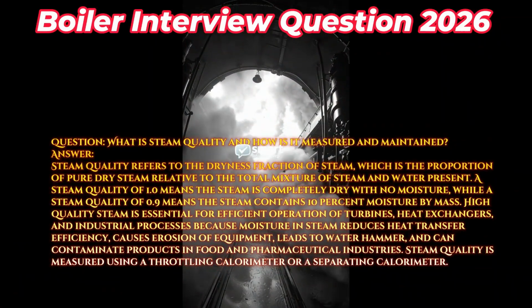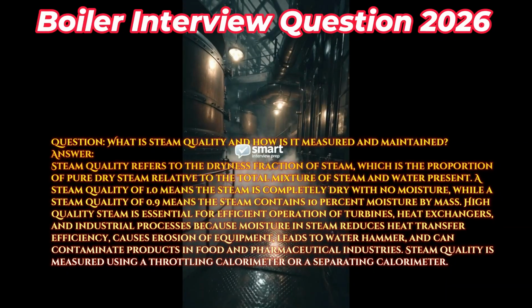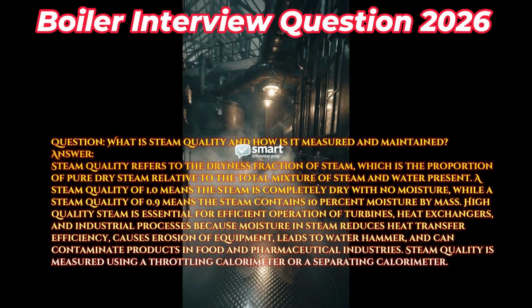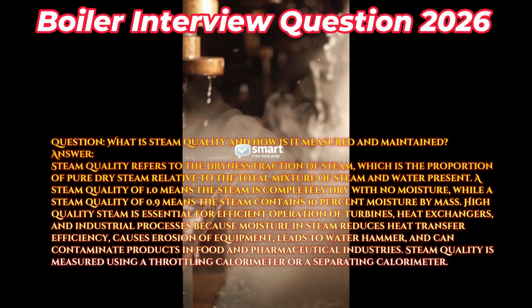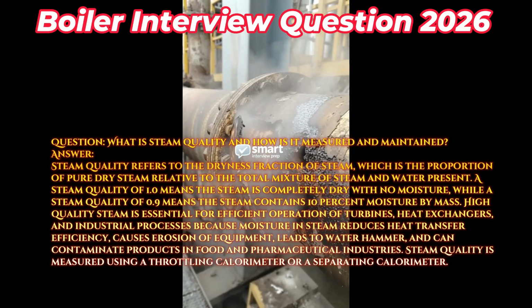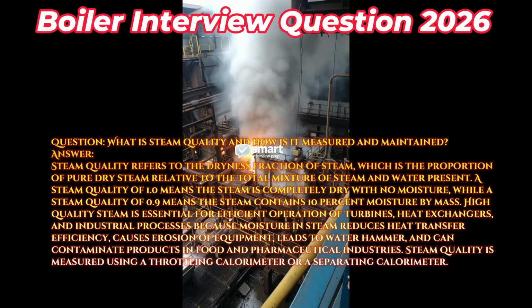Question: what is steam quality and how is it measured and maintained? Answer: steam quality refers to the dryness fraction of steam, which is the proportion of pure dry steam relative to the total mixture of steam and water present. A steam quality of 1.0 means the steam is completely dry with no moisture, while a steam quality of 0.9 means the steam contains 10% moisture by mass.